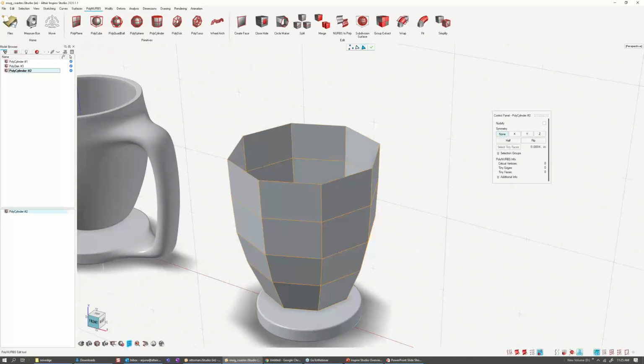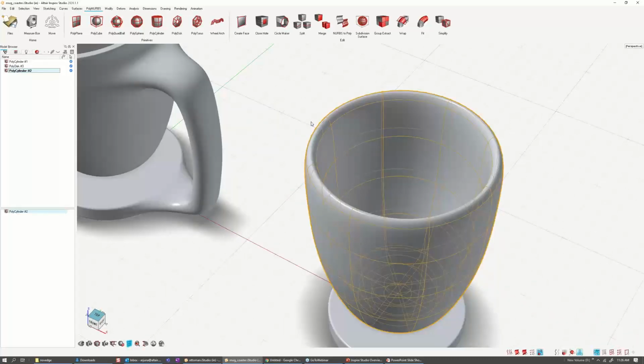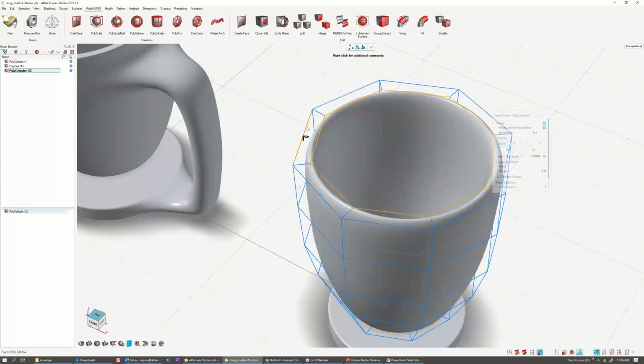and hit done. So this way we started with the cylinder and quickly manipulated it. Now when I hit N on the keyboard, this is what it looks like. Again, as I was saying earlier, the top seems to be very smooth. I can make it a bit more sharp by adding a creasing effect. So I'm going to hold Alt and select this loop, and Control Alt and select this loop, and just increase the strength a little bit.